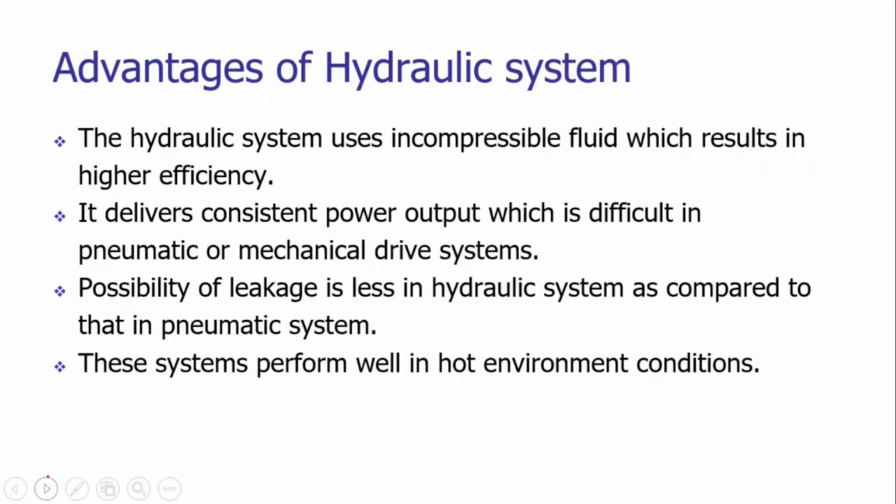Hydraulic systems offer very good advantages. The hydraulic systems have higher efficiencies. We are using incompressible fluid, which results in very good efficiency. The hydraulic systems deliver consistent power, which is difficult in other prime movers such as pneumatics and mechanical drive systems.